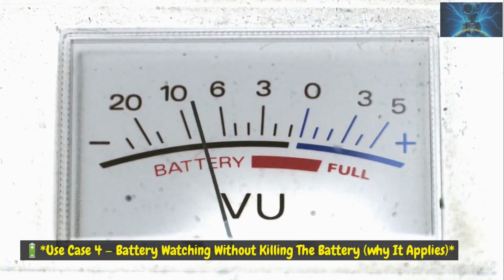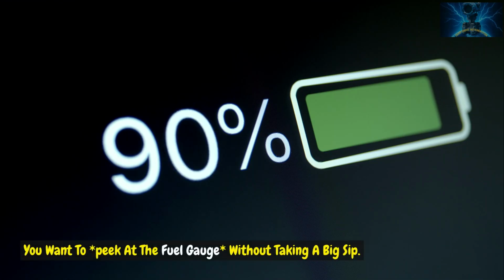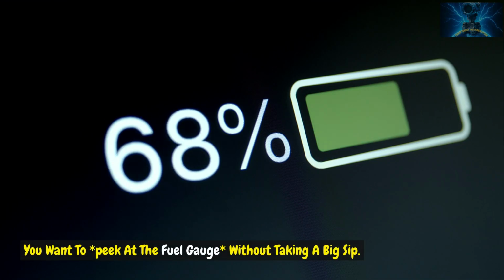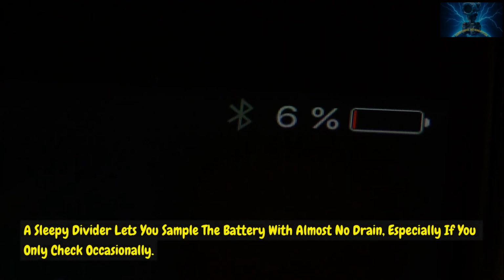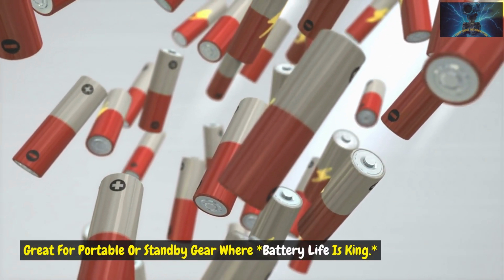Use case 4: battery watching without killing the battery. Why it applies: you want to peek at the fuel gauge without taking a big sip. A sleepy divider lets you sample the battery with almost no drain, especially if you only check occasionally. Great for portable or standby gear where battery life is king.